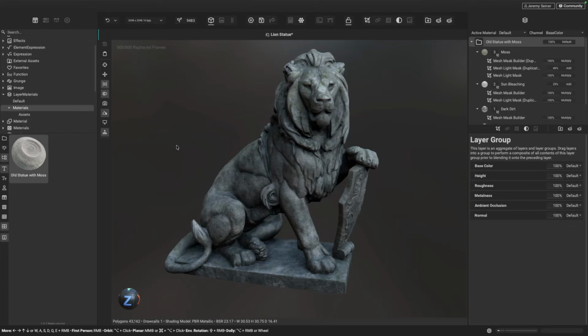You've seen how we can now take a high poly and a low poly model, and we can bake all the high poly details and transfer it onto the surface of that low poly asset that we have here, and then be able to view those mesh maps in InstaMAT, and also utilize them quickly using things like smart prefab layer materials and other types of effects in InstaMAT Studio. So thanks a bunch for watching this video on getting started with baking mesh maps for asset texturing projects.